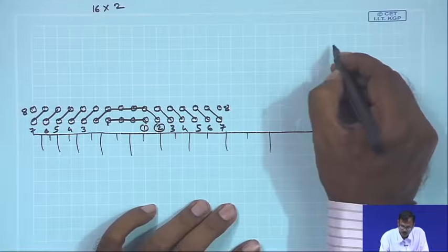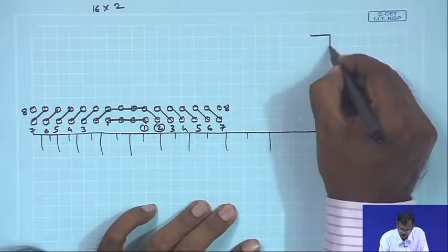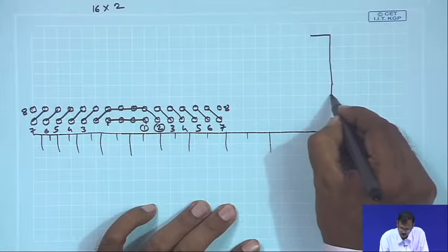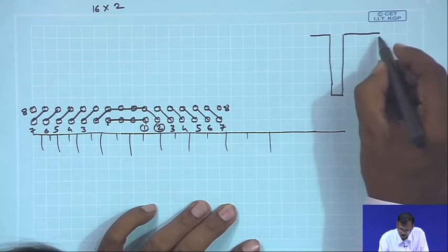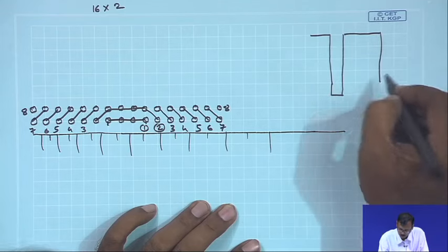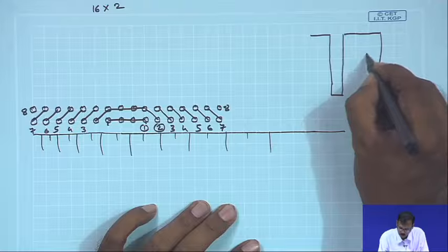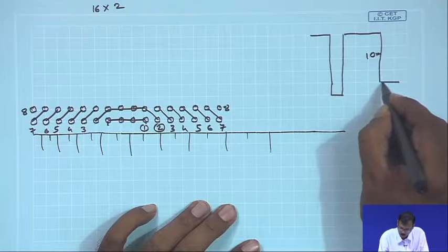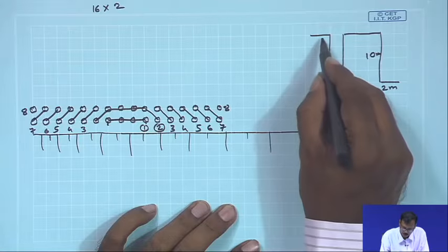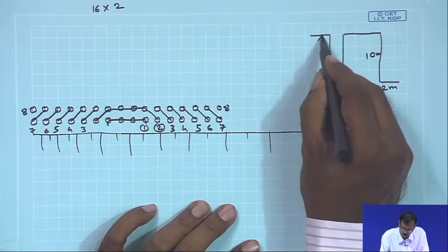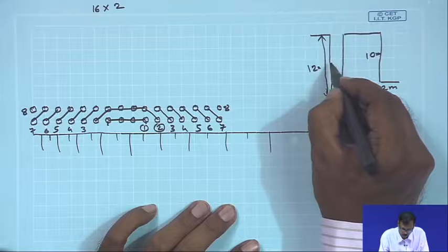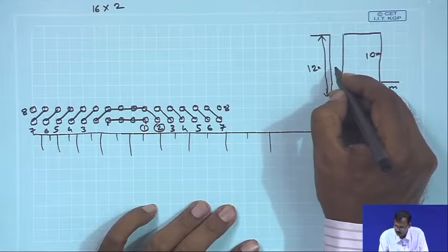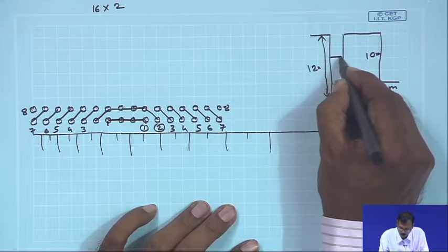If you see the section of the holes, so this is 10 meter, this is subgrade drilling of 2 meter. So, this is of 12 meter, we will drill, we will provide the explosive up to 8.4 meter.